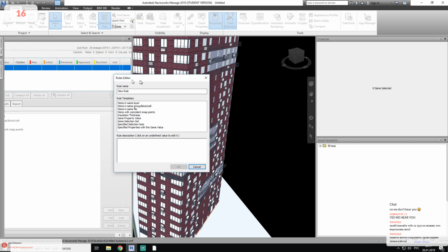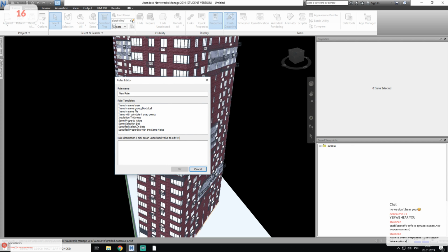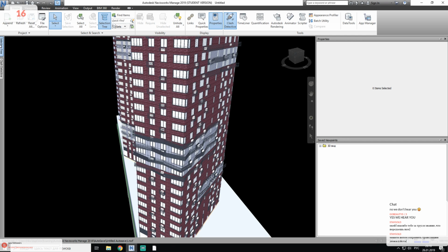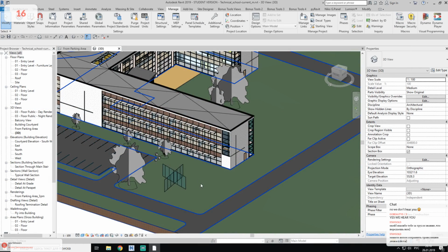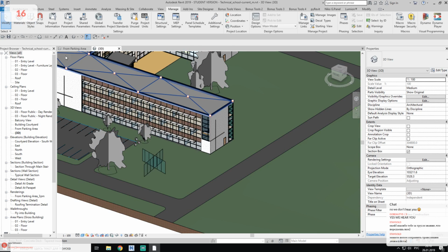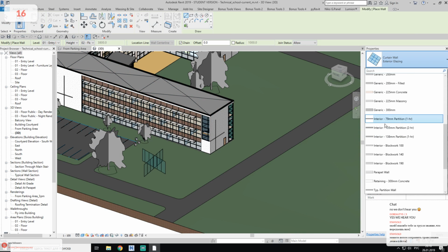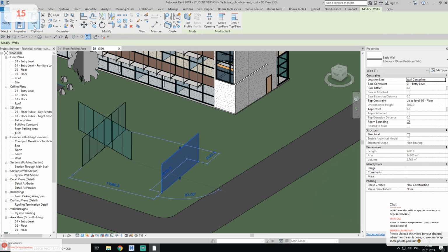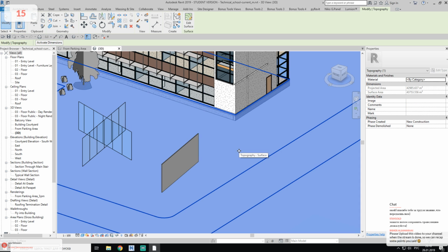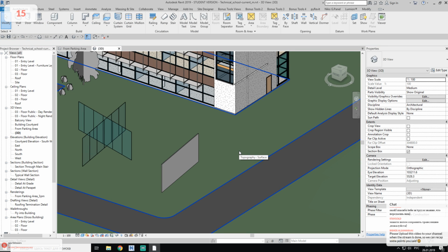Let's select the new rules. Same property, same set, same file, same group, block, this one. Okay, we can create our own rule and put it here if you want. For example, you want to see walls that are in the same position. Say you have one wall, let's say I create a wall like this for you, and you have another wall in the same position like this. Let's say your colleague didn't see it and created a new wall inside the same wall.